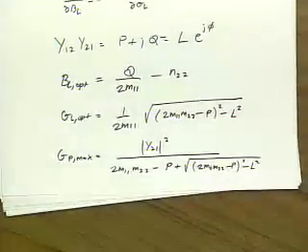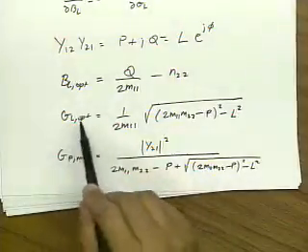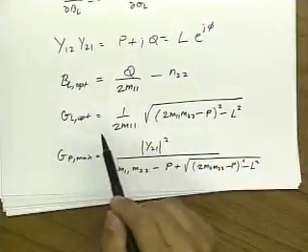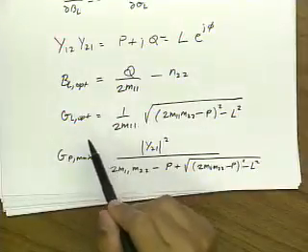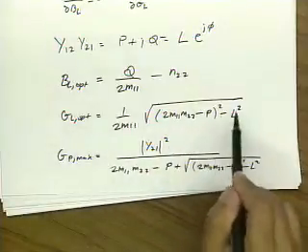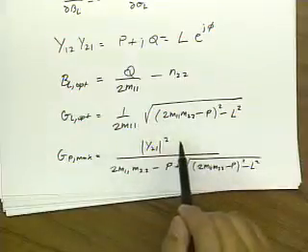Now don't copy this down. The important thing is to notice that this is a conductance, so it has to be positive. Negative conductance doesn't exist physically, at least not as a passive termination. So for this to exist, this term has to be bigger than this term, and that's exactly the condition we talked about earlier under which a solution exists.